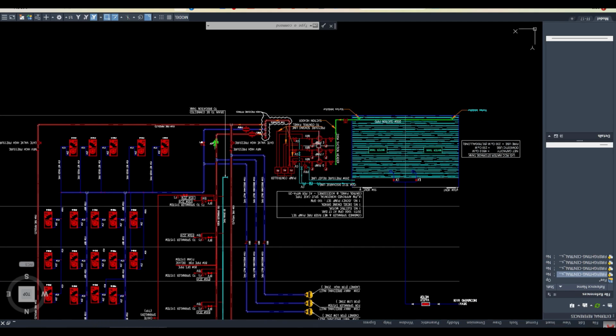I'll just quickly refresh once again that the fire life safety system, we call it FLS system, is a system which is designed to protect the lives in the building. This is designed based on codes and standards, and NFPA is the most favored, you can say the most famous code around the world. Even all the countries have their own codes, but most of them are following NFPA.